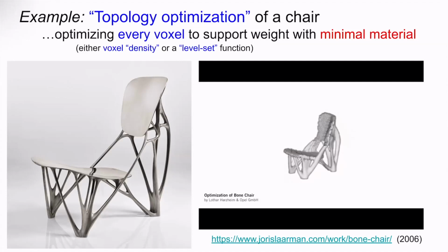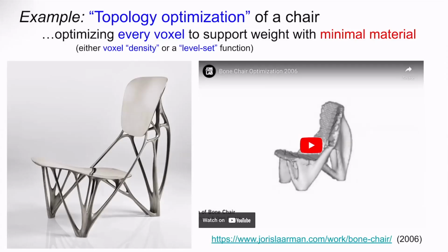And even though there's a zillion parameters, going in the downhill direction allows you to continuously evolve that into this structure. And so it continuously shaves away metal, varying all million parameters at once. And it decides to put this strange arrangement of holes here to make this chair.